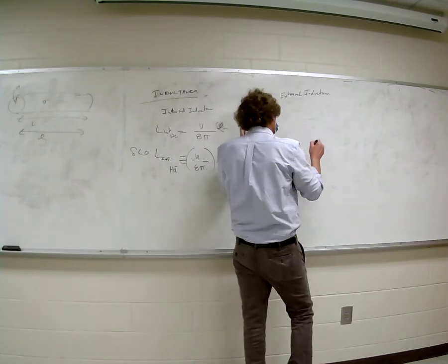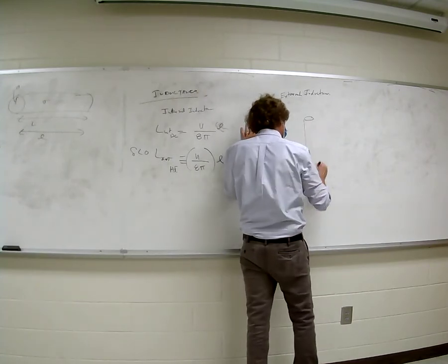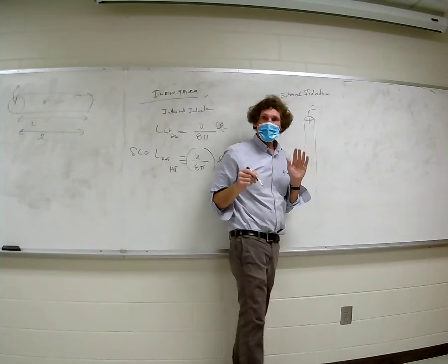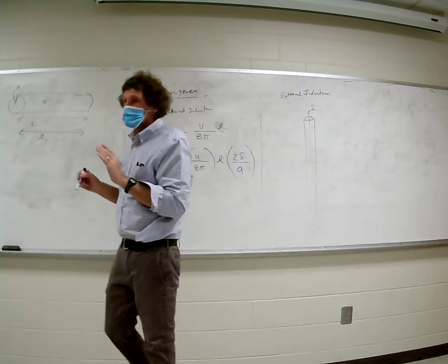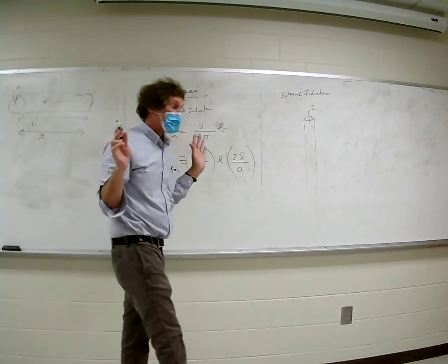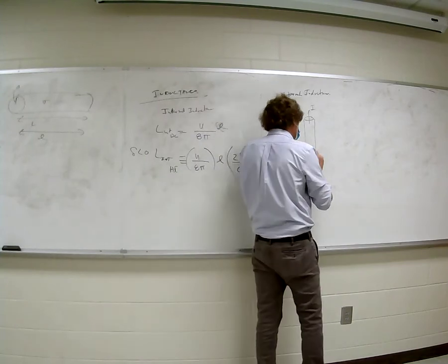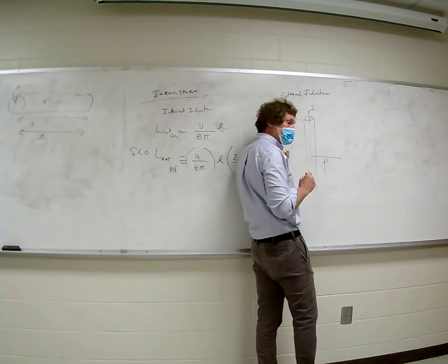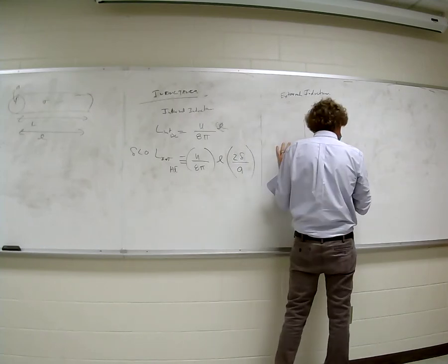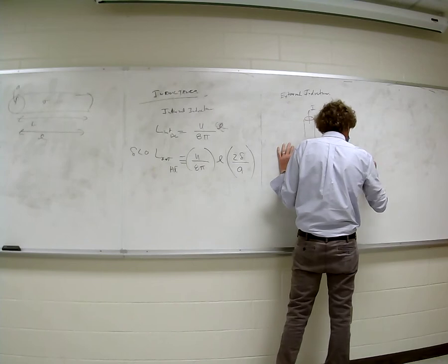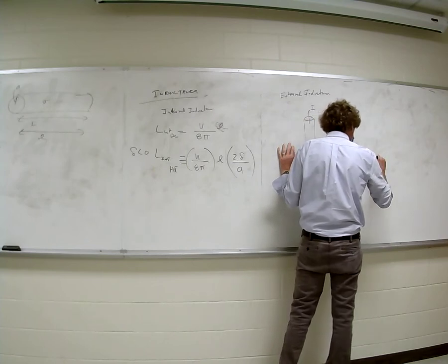When you think about this, just think about a wire infinitely long with a current I. Infinitely long. This is a first order approximation of a power line. All right? Let's assume there's no return path. Well, if we come out here at a distance rho away from the center, then we know that the actual H field would be I over 2 pi rho in the A phi direction.